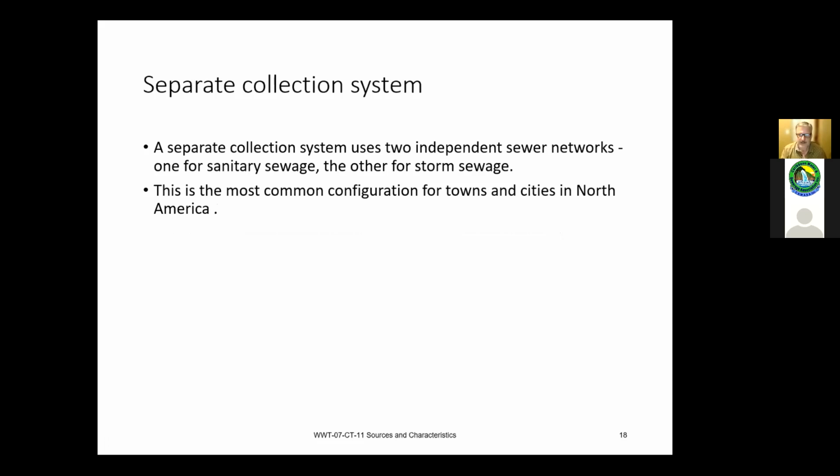What we're finding right now is we've done a lot of painstaking work to reduce water consumption, which is fantastic for the water guys, but didn't turn out so well for wastewater. Your systems are designed to work on a certain amount of flow and load, with flow going through the system so things aren't settling out. When it gets to the treatment facility, it's expecting to see a certain combination of flow and load. What we're finding is our loading is steadily and dramatically increasing, and our flows are dropping off. So we're winding up using potable water more to flush the lines and keep everything moving and fresh so it doesn't go septic. Then we have to adjust how we set up our plant to perform treatment. We're also looking at potential different forms of treatment to deal with this higher loading and less flow.